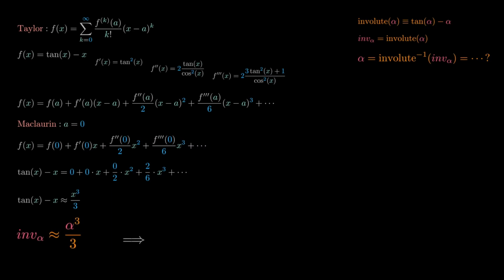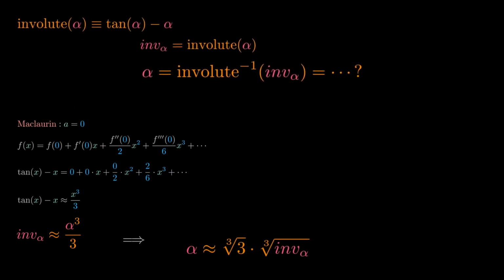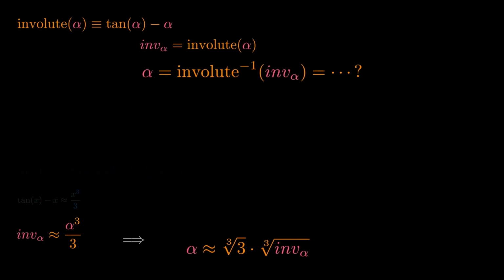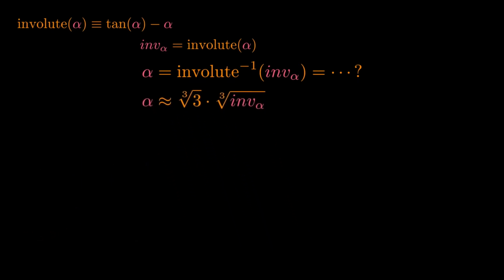Determining the inverse involute is now easy. However, Maclaurin imposes that his series be accurate only in the vicinity of 0. For our needs we work with angles varying from 14 to 35 degrees, which corresponds to values ranging from 0.24 to 0.61 radian. I propose corrections to reduce the inaccuracy due to this deviation from 0.